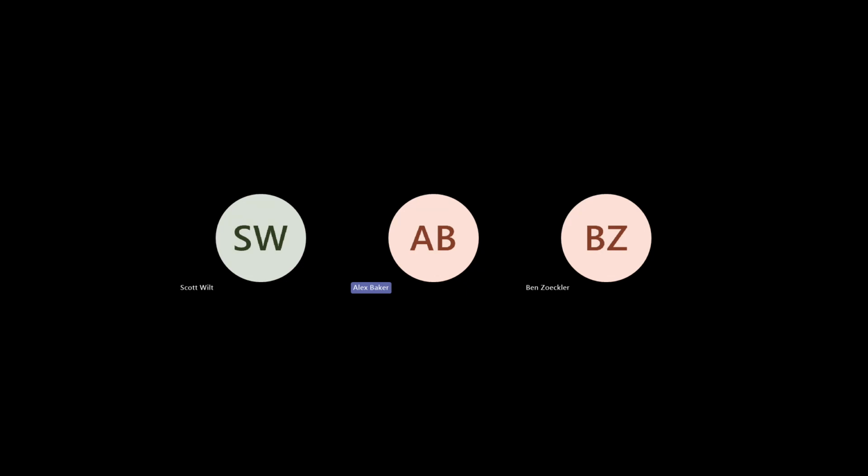If you take a cross section of the mold after the cooling analysis is completed, you can output a time series animation, which is effectively just playing the pictures of each of the time steps back to back with one another. And that's not only for the cooling time steps, that's also for the filling, packing, and mold open time steps as well.